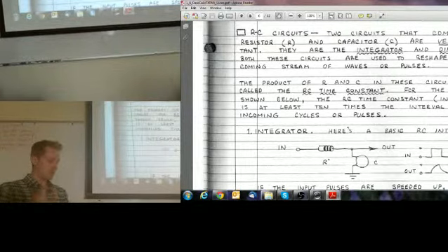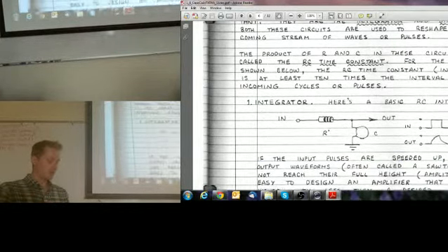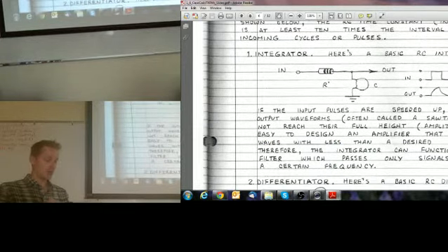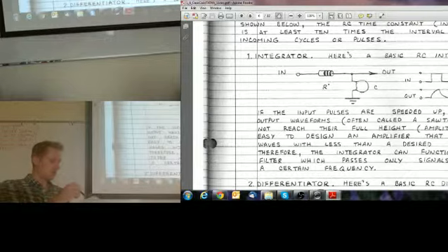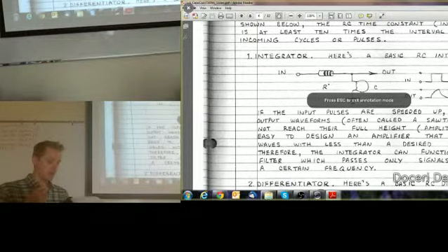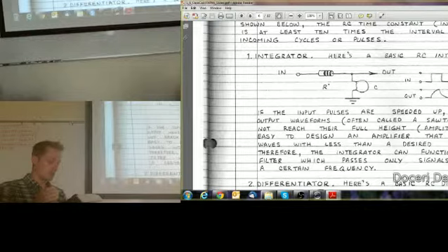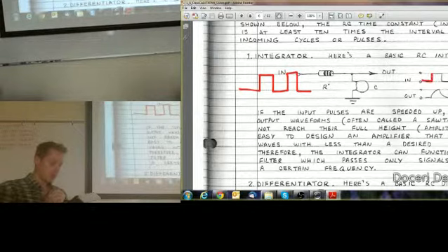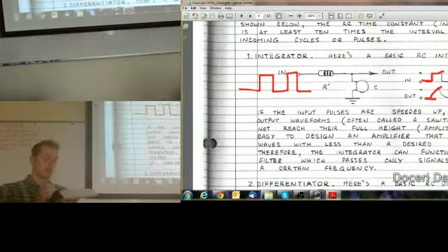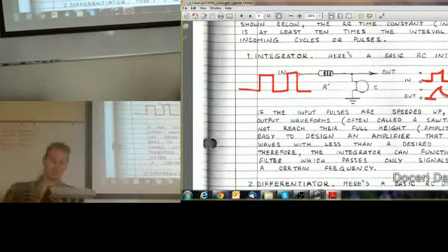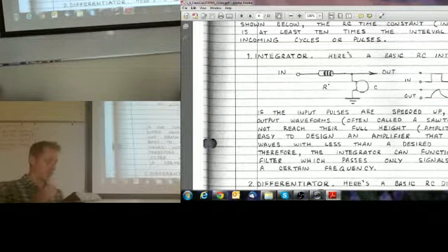Okay, so RC circuit. You can also use a resistor and capacitor in series to get waveform generators. So we talked about the rise time and the fall time. It takes a certain amount of time to rise. If you put a square wave on the input, on the output the signal is not going to instantly rise. It's going to be slow. And then when the signal falls, it's going to have a delay time as well. So what winds up happening is that you can get a sawtooth type waveform. So you can use it as a waveform generator.